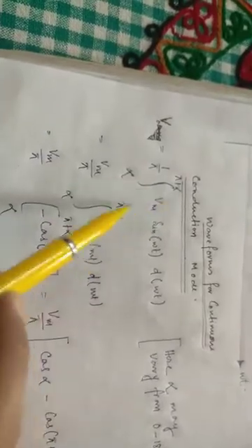Now from the waveform we can calculate the output average voltage. This is the formula for the average voltage. Here I have shown that alpha may vary from 0 to 180 degrees. So the output voltage is 1 by pi, integral from alpha to pi plus alpha of Vm sin omega t d omega t. After calculation, it becomes 2 Vm by pi cos alpha.